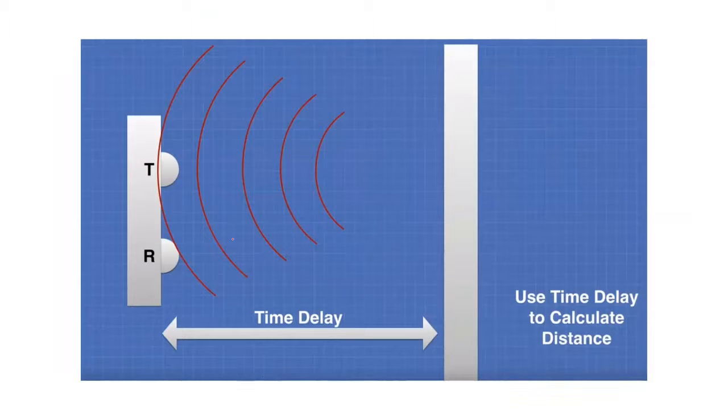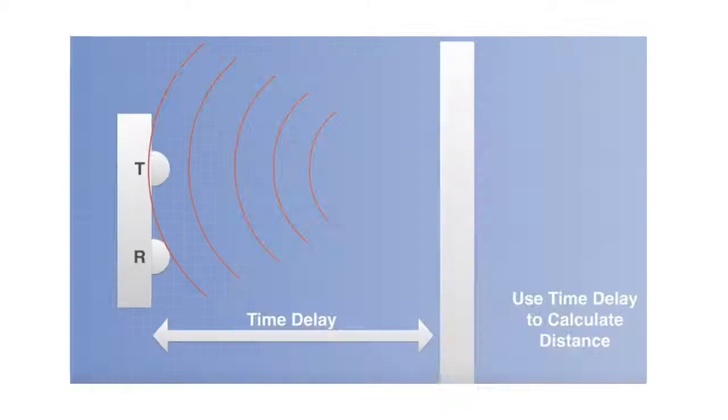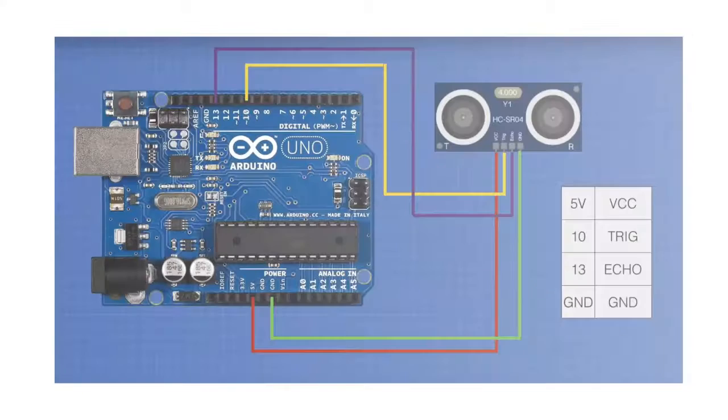And how do we know the distance? You calculate the distance based on the time delay. As the transmitter transmits the sound, the receiver picks it up. The time between the transmission and the echo actually reaching the receiver, that time delay is what is calculated into the distance. Maybe that is another thing we can talk about. But generally, I think we are on the same page.